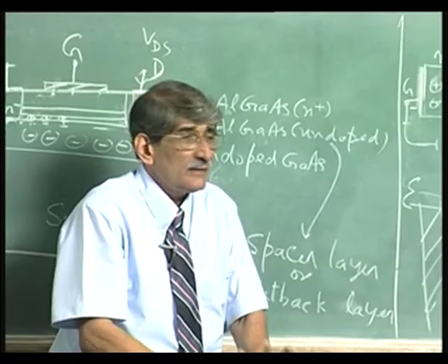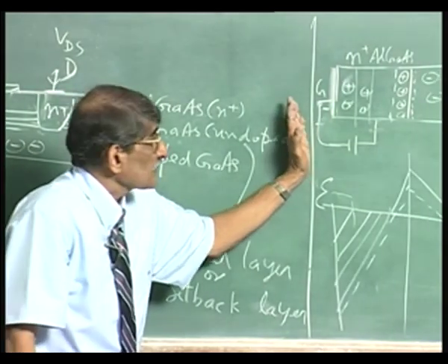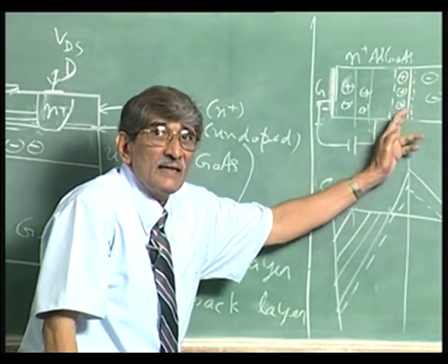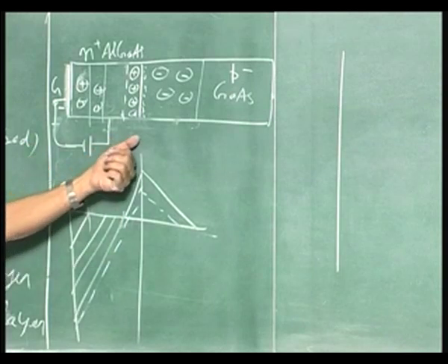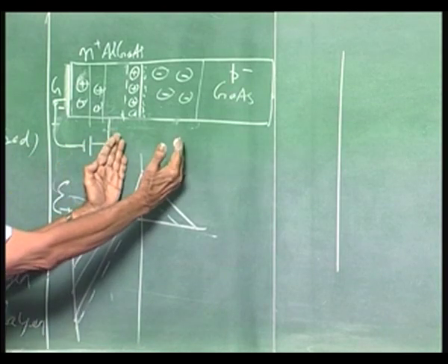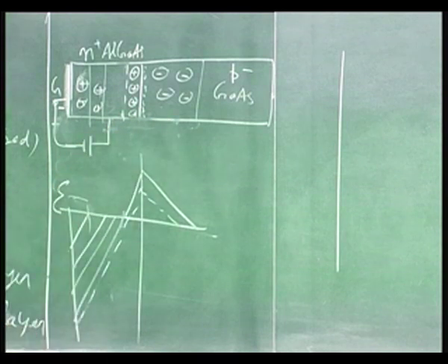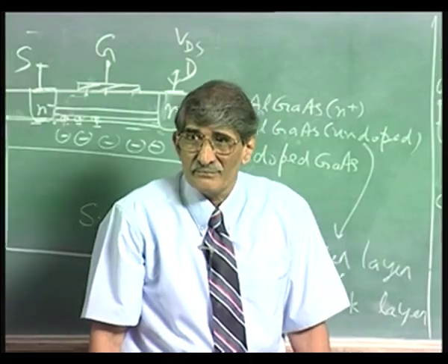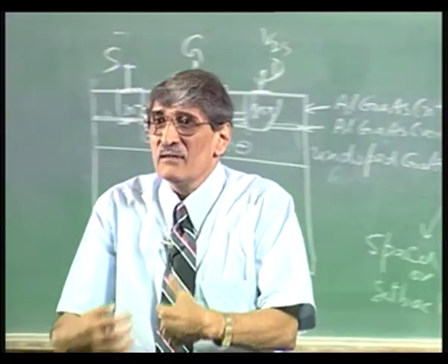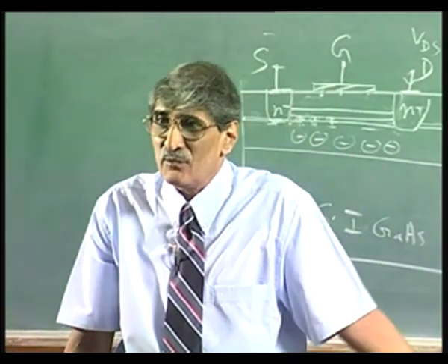The idea is this: gate control can push the depletion layer to this region and can remove the charge from here. More negative I make, less charge, less depletion layer width, that is a forward bias across that. How much I must apply here is equal to delta E c by q. We will discuss what actually is the threshold voltage of this MOSFET next lecture.